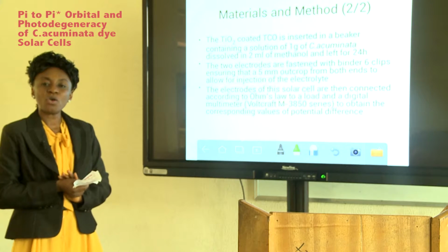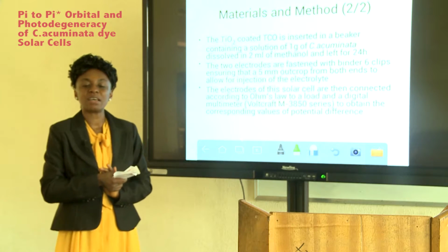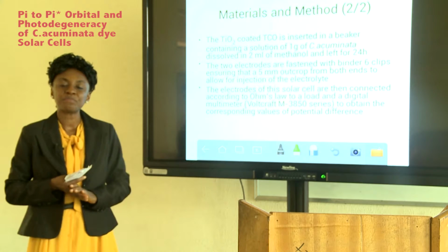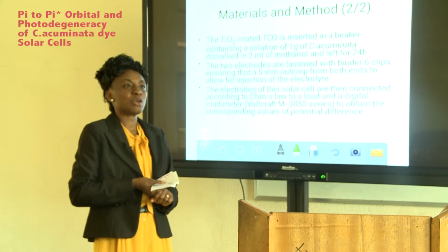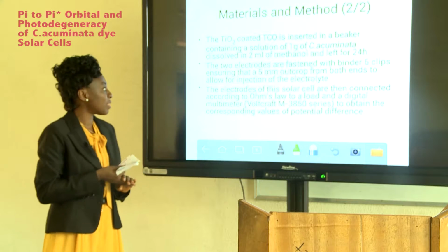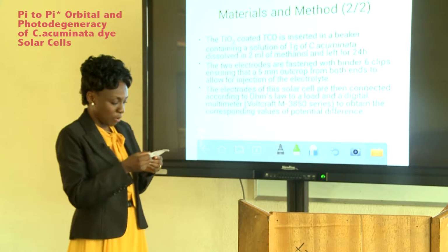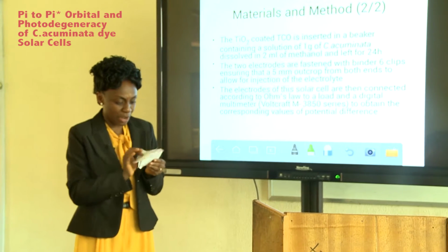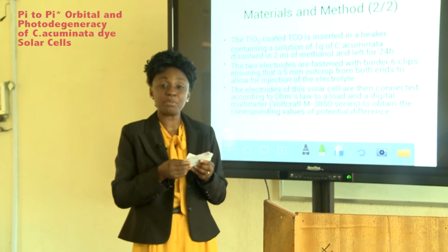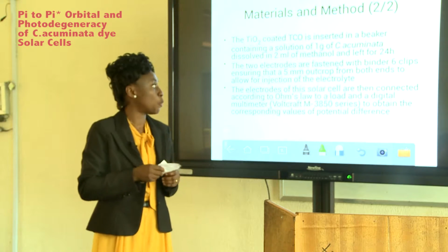The titanium oxide was fabricated using the sintering method. The oven was set to about 450 degrees Celsius after applying the doctor blade method. The active area was just about 25 millimeters by 4.5 millimeters of the ITO.